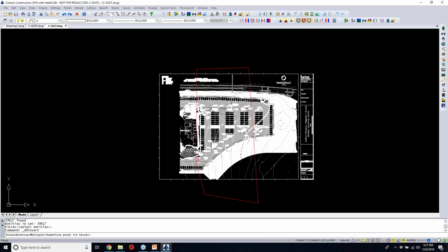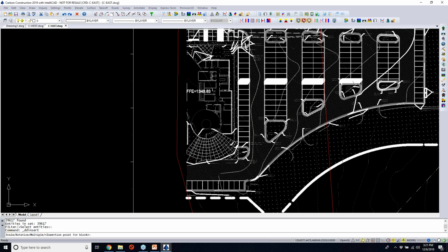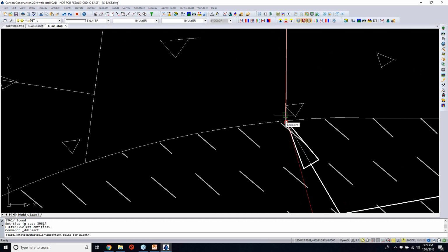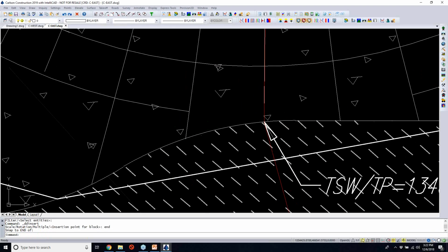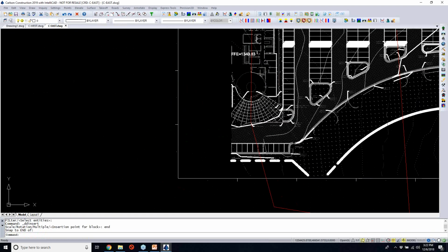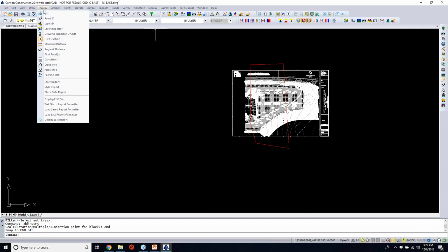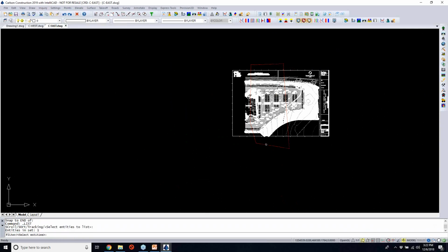And when I go through and put it in here, then I want to make very certain now that I get the proper insertion point. And that would be the endpoint again of the line that I had put it in at, and I want to make sure I get my endpoint snap set up here. And once I have it in there, that should be exactly where I need it to be. And at this point, I think, okay, this is where I about need it to be, and right now if I list it, I can just do it from my keyboard here in query and then list. This should be a single entity as a block insert.